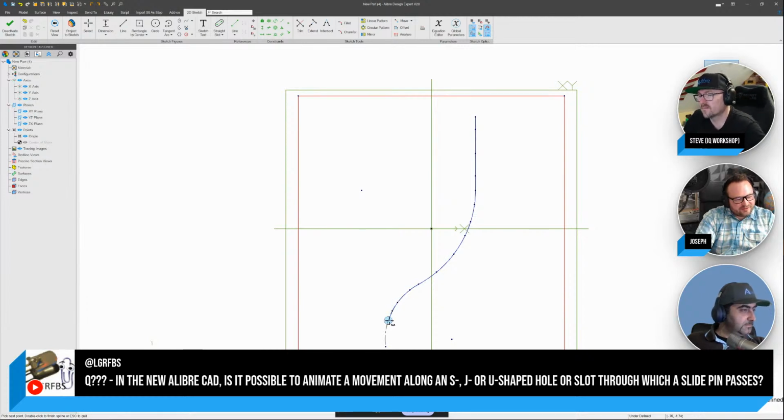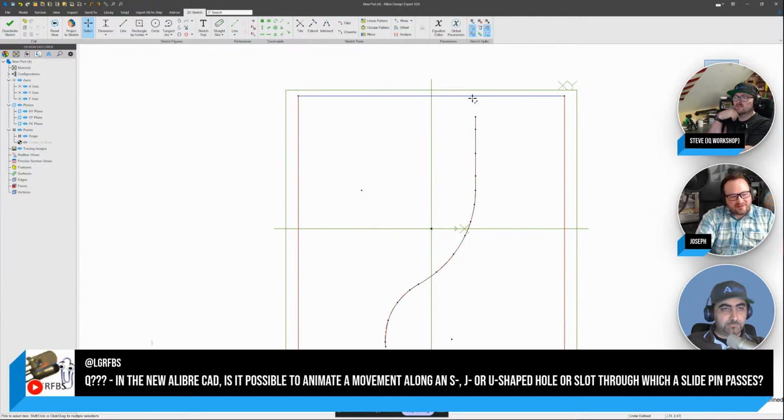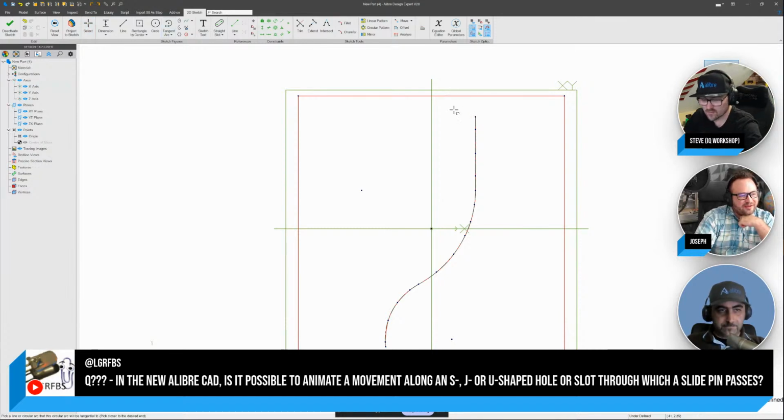And I extruded this. What this does is it follows this arc of a constant radius really closely. And then if I extrude a slot that has the spline that makes it just one face, could I set something circular tangent to that one spline face so it follows the path? It would come down to, can you set something tangent to something that is a spline-derived face in Alibre? Not sure. I almost want to do just a quick little test.